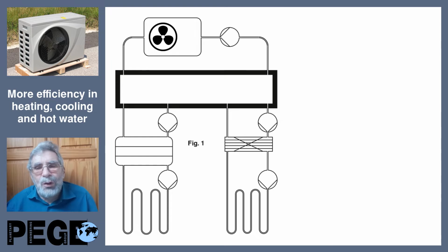So we look for the first patent. We make a big low temperature storage, very big. Even at the small German next generation house standard size, 40 cubic meters. And we have an air heat pump or more than one air heat pump. And the task of the air heat pump is only to fill this low temperature heat storage up to maybe 19 degrees in usual cases.